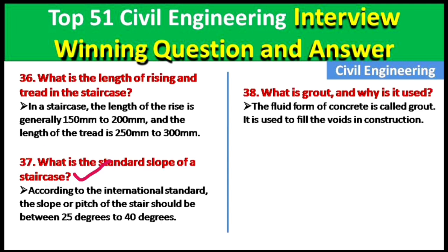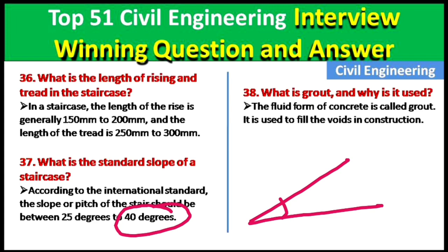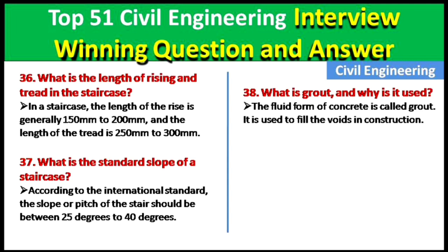This point we have already discussed, that we should not increase the angle between the staircase and horizontal more than 40 degrees. So if we are constructing a staircase, then the angle should not be more than 40 degrees and less than 25 degrees. Okay, point number 38 is what is grout and why it is used.